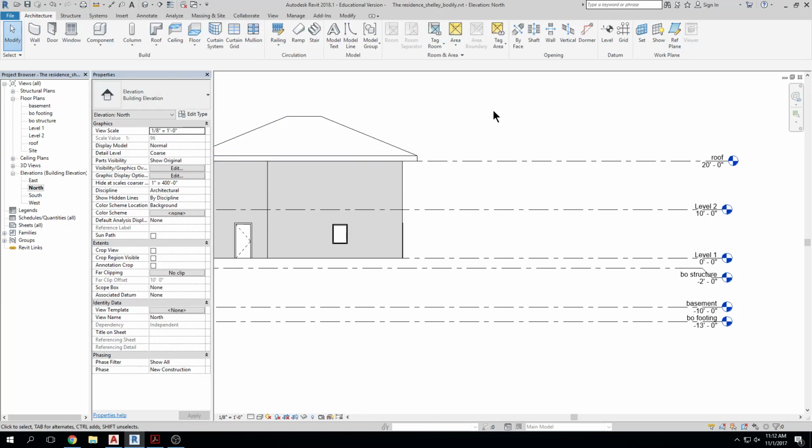So to create a footing and foundation system underneath your projects, which you're going to have to do, in an architectural drawing set you think, well, you do have to draw footings and foundations, even though they will be specified by the structural engineer. The reason we do it is so that we can show design intent of the space below and define the building envelope. We essentially tell the structural engineer where we want these things to happen, and then they engineer them and fine tune them. We make our best guess as to how big items are going to be. In general, a foundation wall can be 8, 10, or 12 inches, and the engineer may say, well, we want a 10-inch one in this case. Okay, great, and we can fine tune things.